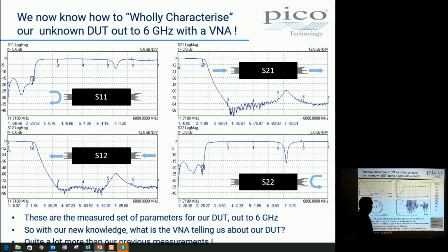The time domain response, that is S21 time domain. Sorry, that's S21, that's S21, that's S21, this one's S11 at the moment. So, does it make sense, if you've only got access to one end of the device, to do an S11 time domain? Yes, you can. It does make sense if you're trying to find, say, distance to fault or whatever.